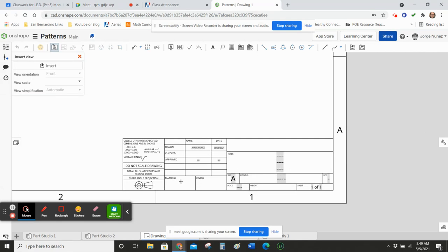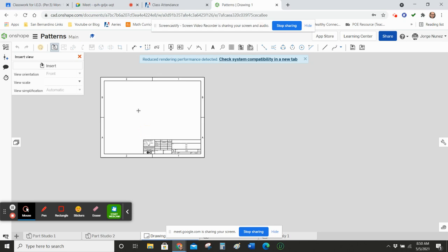So you have a bunch of different projections. You can have the size of the paper. You can have the scale. If you actually add other things within your shape, for example, if you say that it's made out of copper, or aluminum, or certain types of plastic, or wood or whatever, you could add those material properties, and it'll actually populate the weights for it, sometimes even the density, what material it is, the finish, whether it's rough or smooth, etc. So a bunch of other different things that we can do within the program.